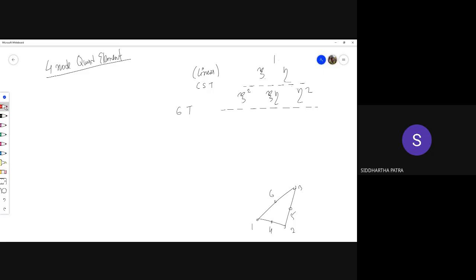This triangle that I'm drawing here with the possible terms in the shape function is known as Pascal's triangle. Similarly, in 3D, there is Pascal's pyramid, involving another natural coordinate, let's say gamma.